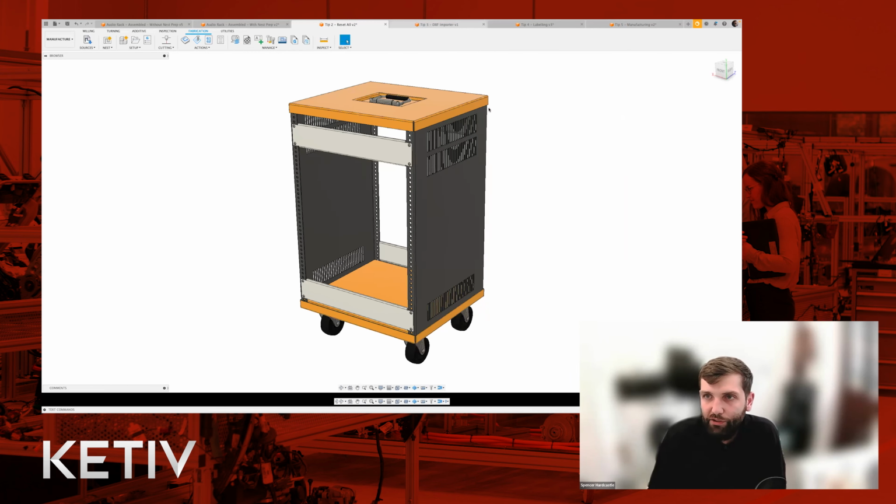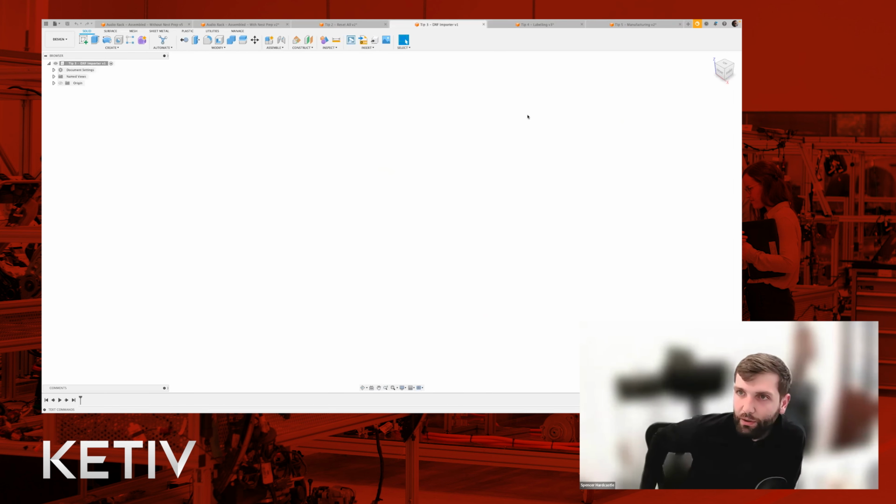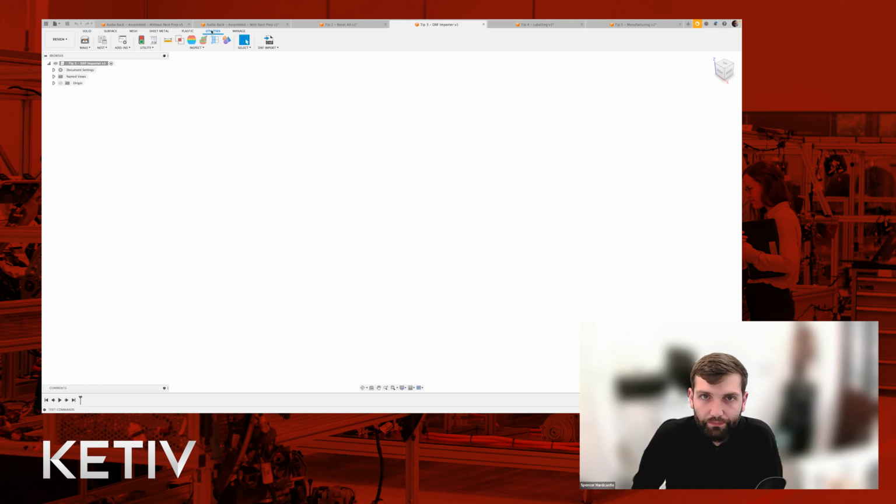So there's an add-in in Fusion. It's called DXF Import. Patrick Rainsbury, if you're on the call or you ever watch this recording, shout out to you. You did a great job of creating something called the DXF Importer. So I'm here in the design workspace, and what I want to do is navigate to utilities. Now, what I've done is I've gone to add-ins.